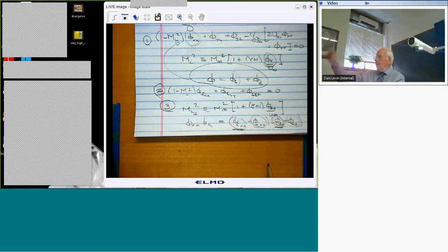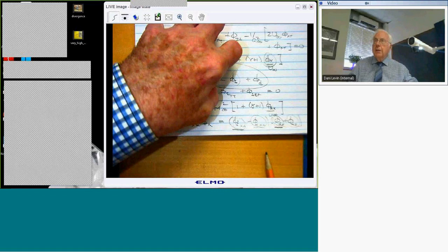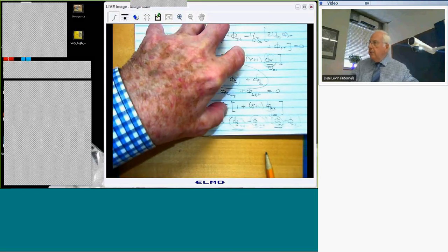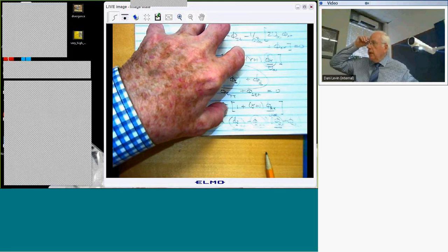And then you can use that representation, compute aerodynamic influence coefficients, and do a flutter calculation in the standard way, even though you got the information from a Navier-Stokes code. But you don't care. All you have is a plot of CL unsteady versus reduced frequency or something, right? So people have done that, and that's a useful thing to do. So even though this particular model isn't used much anymore, the ideas that emanate from that led to people now doing similar things for these more elaborate CFD codes.